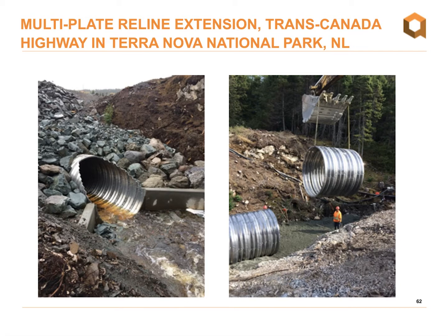So let's jump ahead 2 years. The Trans-Canada Highway above the original tunnel liner in Terra Nova required widening to create a new passing lane and improve the traffic flow through the park. So the existing tunnel liner plate was extended to accommodate the wider road. This shows the versatility of using a segmental structural plate for these applications. You can always extend the length at a further date if the need arises.